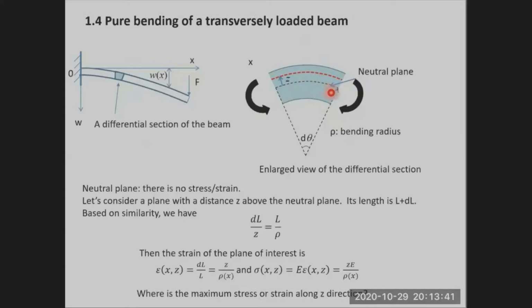So the middle plane is the neutral plane. On the neutral plane, the stress and strain are zero. That's the reason we call it the neutral plane. Above the neutral plane, the material is stretched. Below the neutral plane, the material is compressed. So that's the concept of a neutral plane.